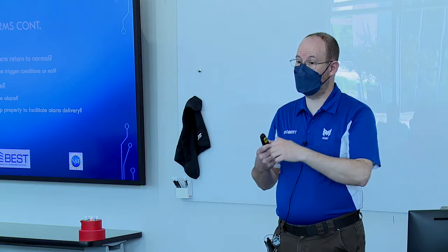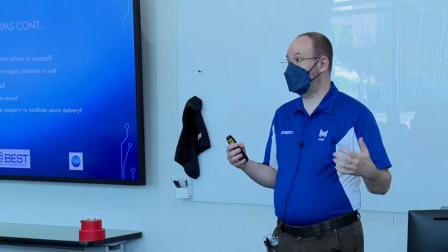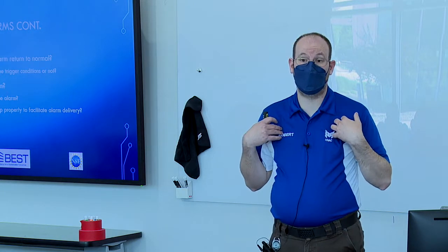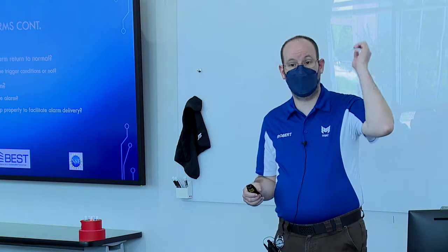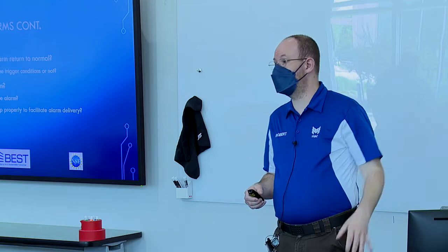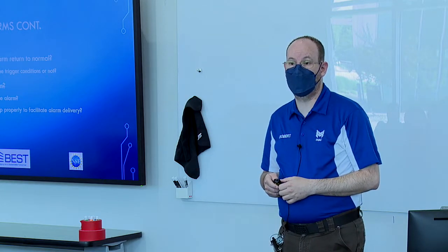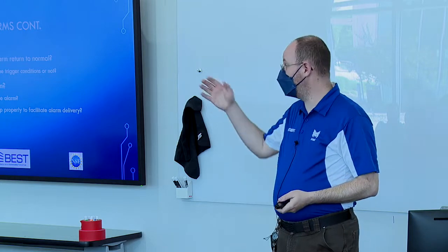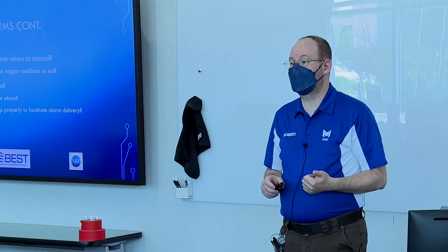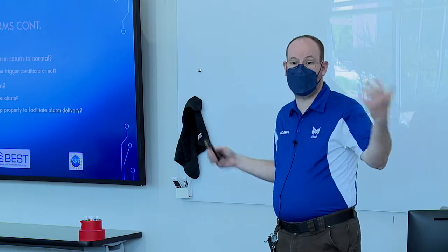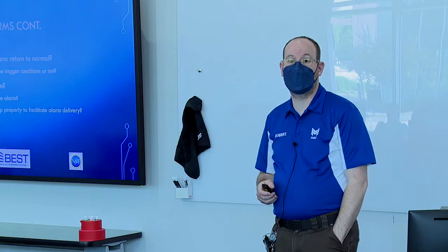You know, on new construction type projects, I didn't have time to do things like properly tuned PID loops. It was throw initial values at it, make sure it's not going to blow anything up, get out. Okay? You're going to check calibration on sensors for air handlers, maybe spot check a couple of VAV boxes, pass that, get it done, get out.